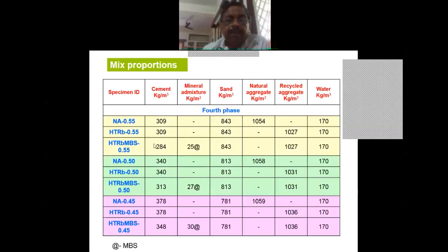When we are using this biomass silica, earlier we saw that when keeping the cement content the same, there is a drastic change in the mechanical properties of the mineral admixture concrete, which is higher. So we tried to replace the cement itself, and we are not changing the recycled aggregate quantity. We have taken 8% replacement of cement, which is a very small quantity.